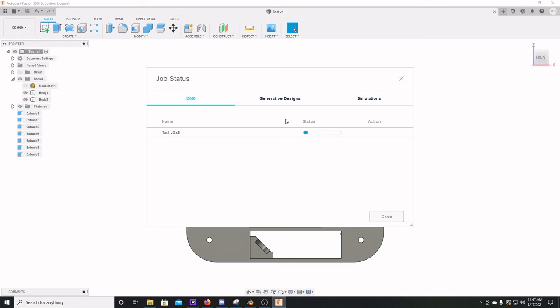Now, you could do that in AutoCAD, which you're comfortable with, or you can continue doing that in Fusion 360. I continue doing it in Fusion 360 because I could easily upload any of the mesh files that have previously been altered or are just a part of the project, and that helps me see how I need to alter or change or even make something in the first place in order to fit the cat door STL that I found online.